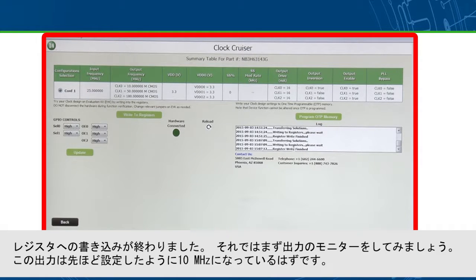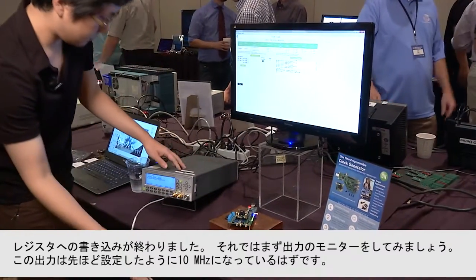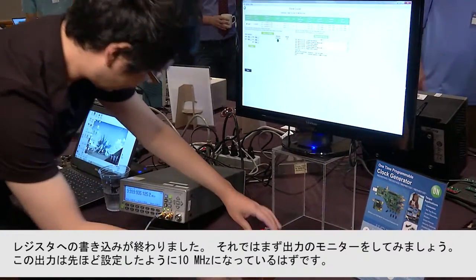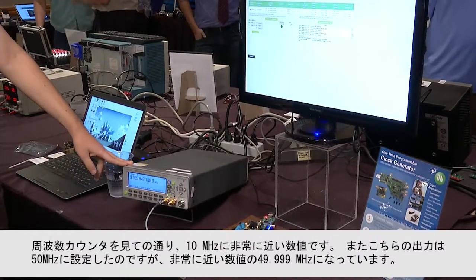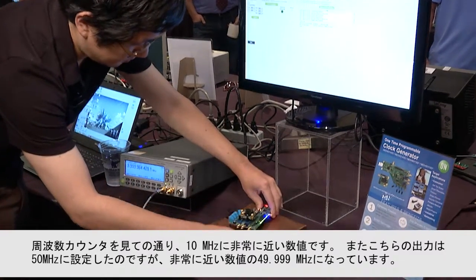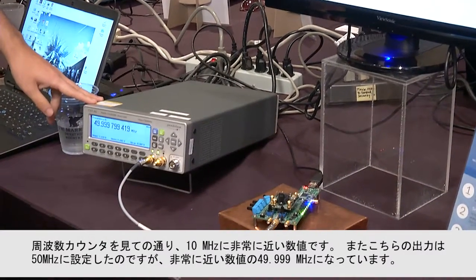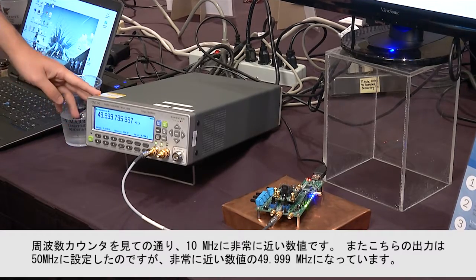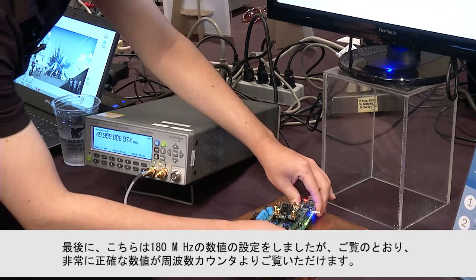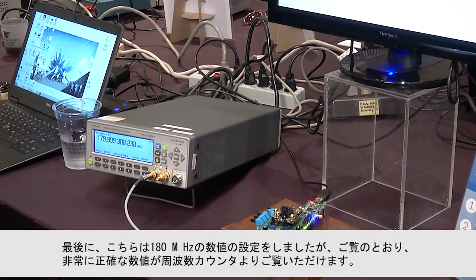Register write finished. So now I switch. First we'll monitor the first output. This one should be 10 megahertz as we just set. And you can see on the counter that it is very, very close to 10 megahertz. Okay, this one is set to 50 megahertz. We see 49.999 is what the equipment is reading. And lastly, this is the unique one of 180 megahertz. And once again, we see a very accurate result on the frequency counter.